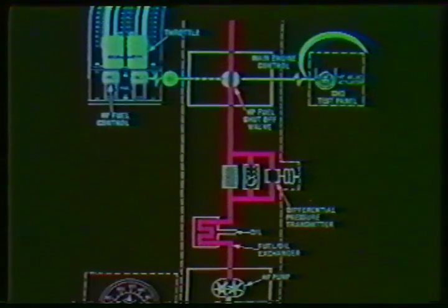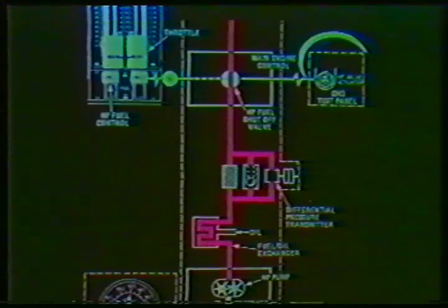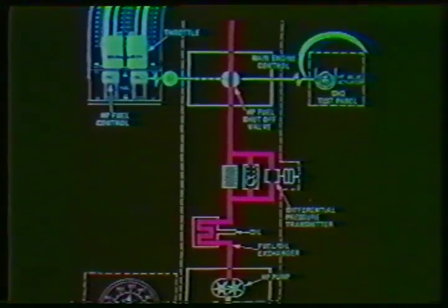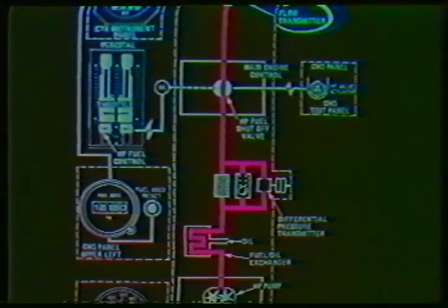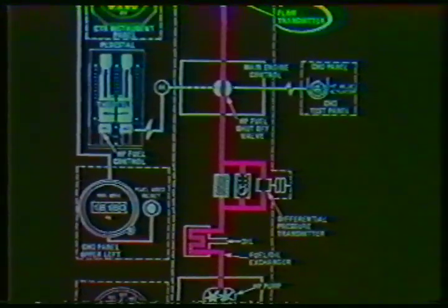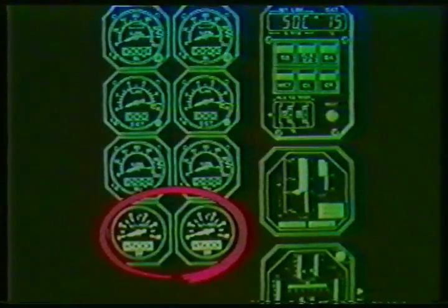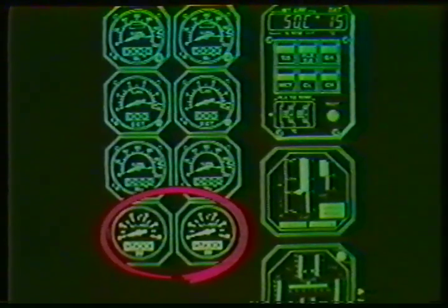A magnetic annunciator, labeled high pressure valve actuator, indicates an electrical failure of the actuator. An associated press-to-test push button is provided to simulate a failure at the high-pressure valve actuator and to test the magnetic annunciator. Before reaching the nozzles, the fuel passes through a flow transmitter. This flow meter gives information to an instantaneous fuel flow indicator labeled fuel flow on the center instrument panel.